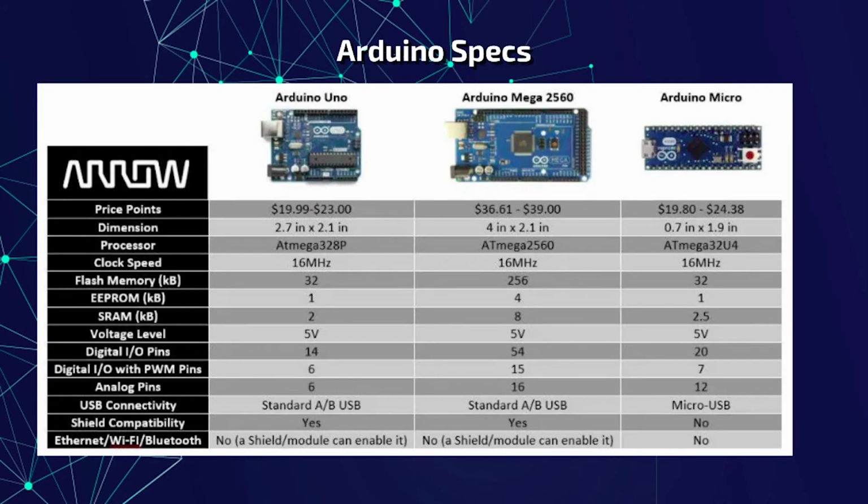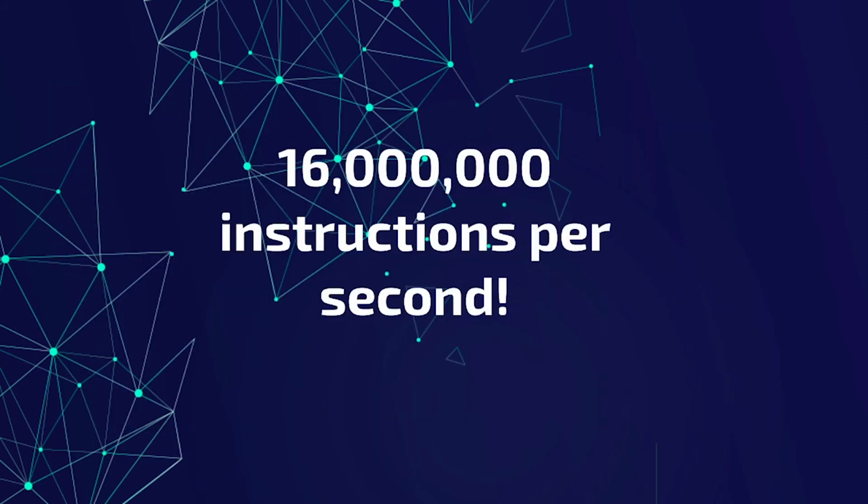The reason that the LED is always lit is because your microcontroller runs too fast. The Arduino Uno runs at 16 MHz. That's 16 million instructions per second. That means that even though it is looping between high and low, it is doing so every 1/16 millionth of a second, and thus we are unable to observe it.